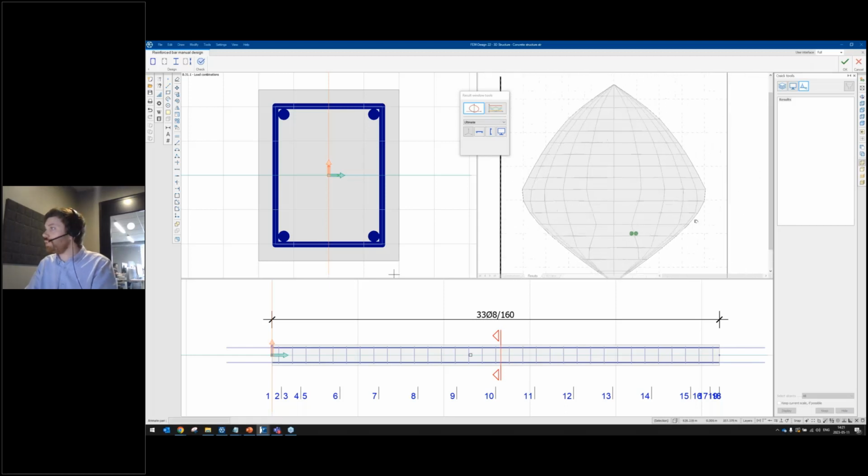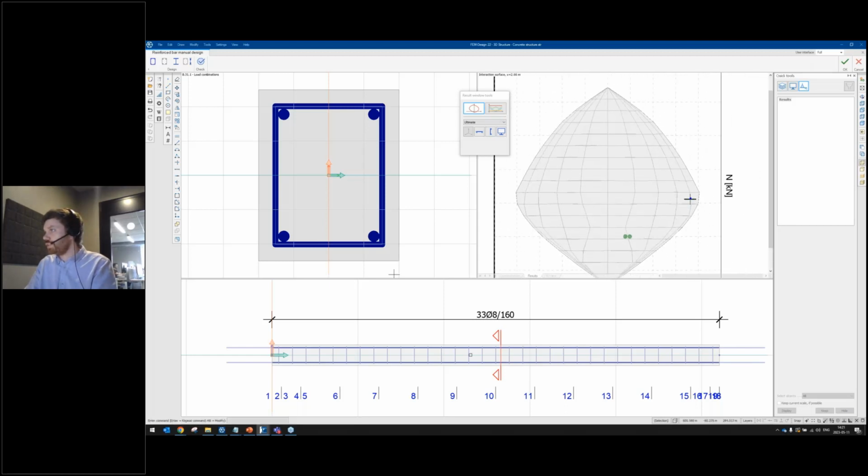So we are not at risk of doing this kind of error. But if we should be maybe up here, you actually rely on the compression force in the section to be able to carry that kind of moment. So in that case, you have to ensure that that compression is always there together with the moment. Otherwise, you will go down to the 0 level of the moment and you will cut the surface of this interaction surface and thus get an overutilization of the cross-section.